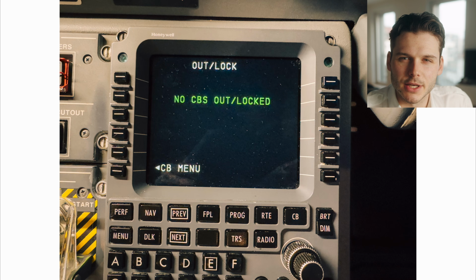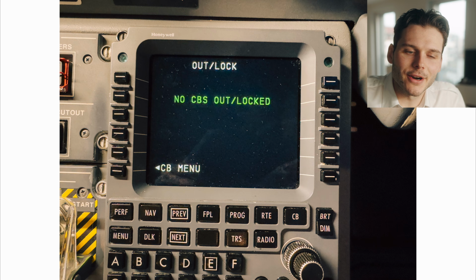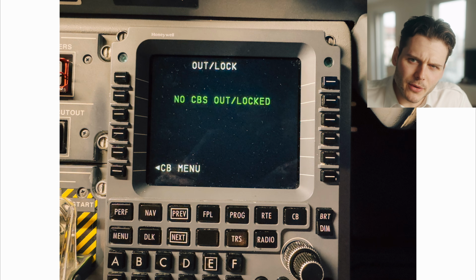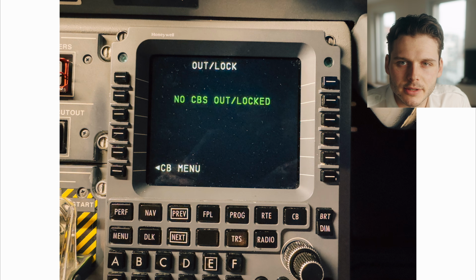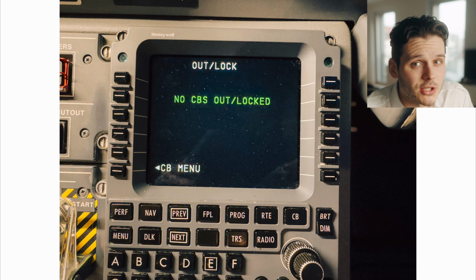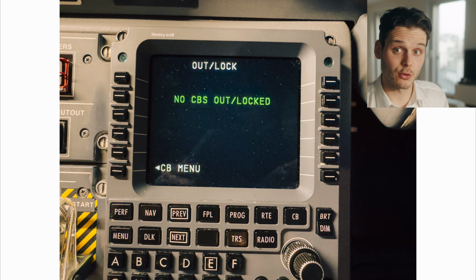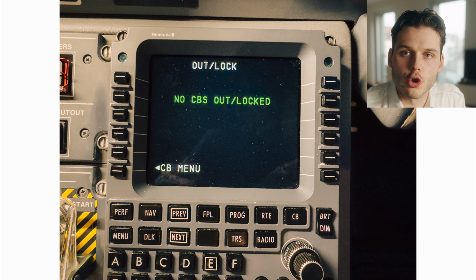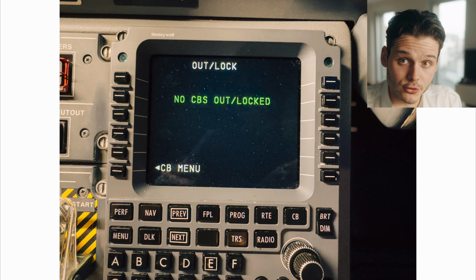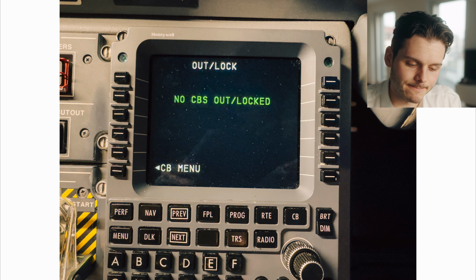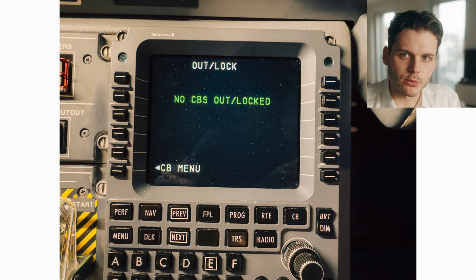So this is it. This is the end of the slideshow. It's really Embraer systems, but really this is not very different on other aircraft, I assume. Some aircraft do not have ram air turbines, like the Boeing 737. The reason for that is that the Boeing 737 can be flown without any electricity, as it is a fly-by-cable aircraft, so traditionally connected with the yoke and the flight controls. So it's called manual reversion. I'm not really sure about any details of that. So they do not require a ram air turbine, actually. Some interesting fact. But we do have one, and Airbus does have one as well.